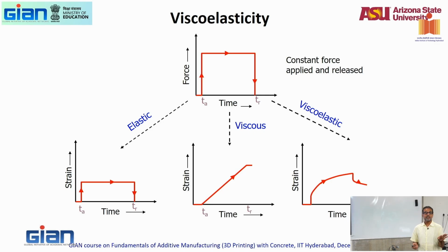Now, the other concept is viscoelasticity. Materials that demonstrate both characteristics of a fluid and a solid, viscoelasticity. But when do they demonstrate is a question. Concrete is a viscoelastic material. Actually, asphalt is an even better example of a viscoelastic material because that demonstrates viscoelasticity very obviously at the operational rates that you see. With temperature, you will see real dependence of viscoelasticity.